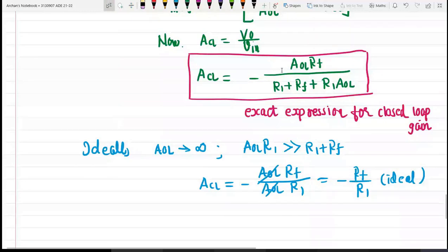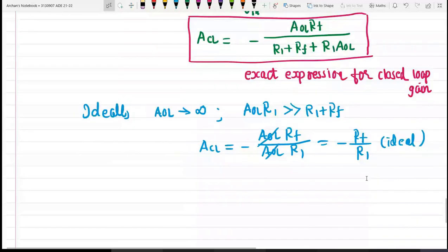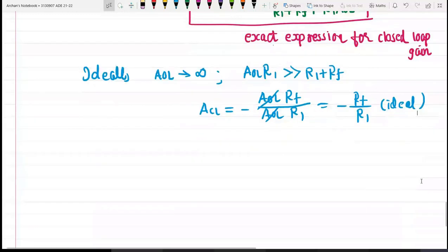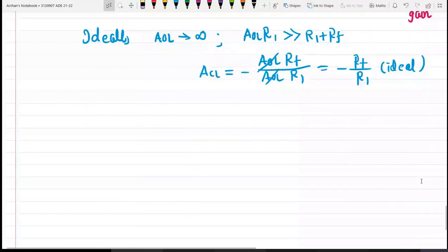Now we will be able to derive a block diagram for this practical inverting amplifier. To obtain the block diagram of the practical inverting amplifier, it is necessary to represent the current summing junction at the input terminals of the amplifier as a voltage summing junction. See, we have input signal V in over here, and this input signal gets amplified.